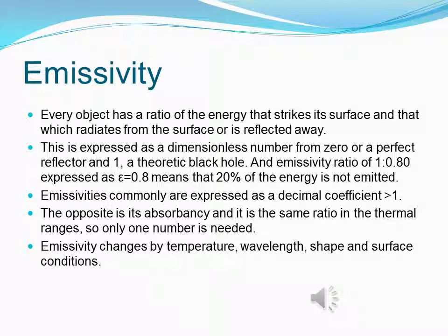But in order to do our testing with a thermal imaging device and with a thermometry, that is a thermal temperature device, we had to know exactly what we're shooting, so we painted black enamel paint on it so we knew exactly what the emissivity was. Otherwise, when you're dealing with large amounts of energy, those numbers would have been significantly off.